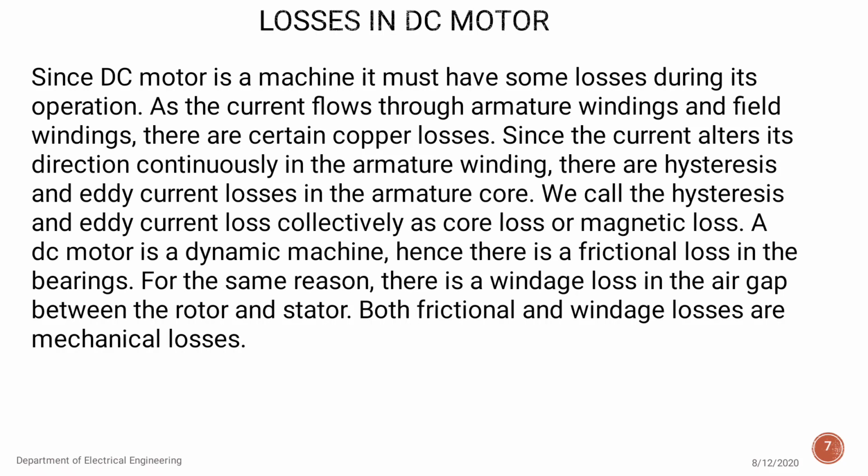Then that current is always alternating in nature, so it is alternating continuously. Due to that, whenever this current flows through the core, at that moment eddy current as well as hysteresis losses will take place, which are also known as magnetic losses as well as core losses.